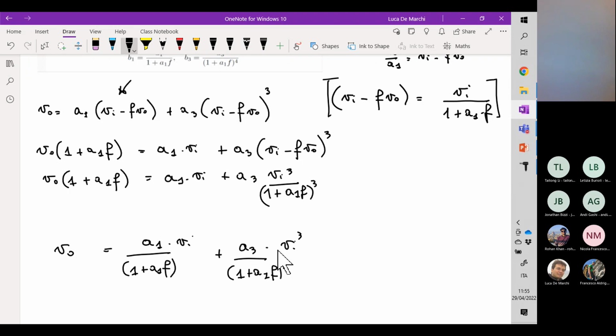What we can do is to start from A0 in dB, and then sketch an asymptotic plot in which whenever we hit the angular frequency corresponding to a given pole, we have a minus 20 dB per decade decrease in the value of the amplitude of the direct path gain A of j omega.